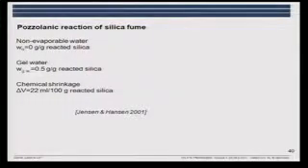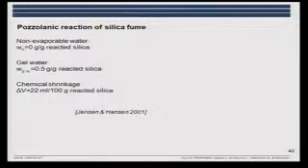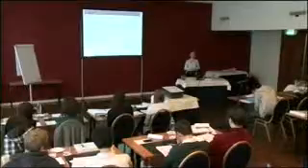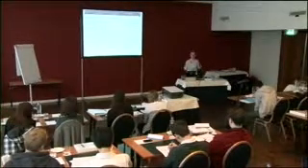Here you see an example of what happens if we start to use silica fume. The constants, I don't know if you recognize, but the change in non-evaporable water is 0. The gel water is 0.5. Compared to the other, it's much less, and the chemical shrinkage is much larger. This is part of the reason that we may have problems with what we call self-desiccation, self-inflicted drying out of the concrete when we use silica fume. So more water is needed from the exterior.